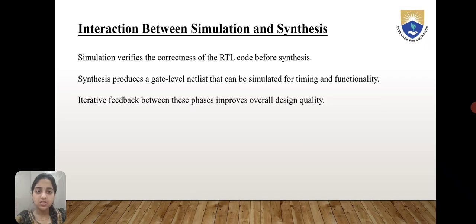Interaction between simulation and synthesis. Simulation verifies the correctness of the RTL code before synthesis. Synthesis produces a gate level netlist that can be simulated for timing and functionality. Iterative feedback between these phases improves overall design quality.